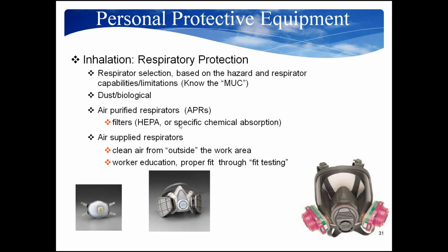The respirator might be just an air purifying respirator, which has filters, such as seen at the bottom here. There might be a HEPA filter or some sort of material to absorb VOCs, for example, or acids. You might have a respirator that's air supplied, so it's clean air from outside of the work area, and it's important that worker education and fit testing occurs.